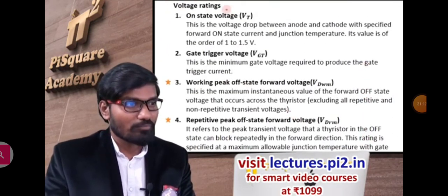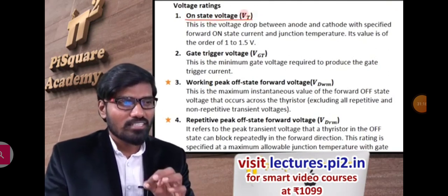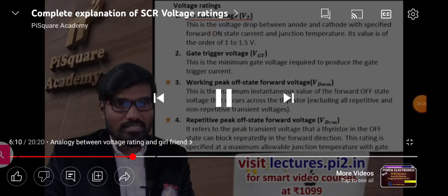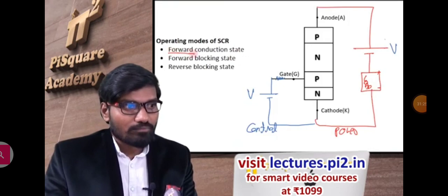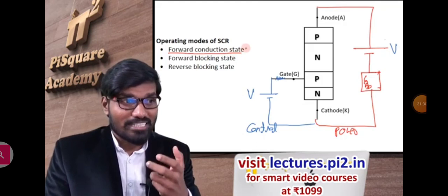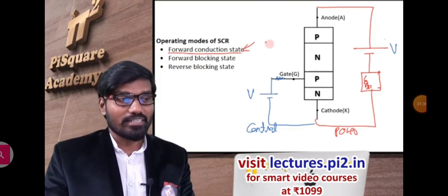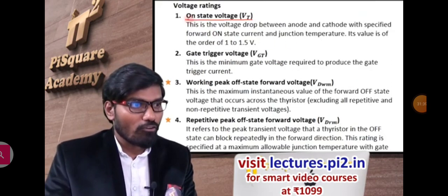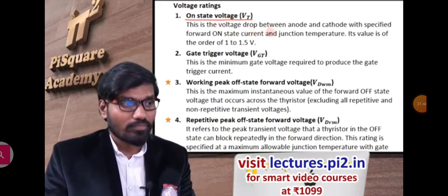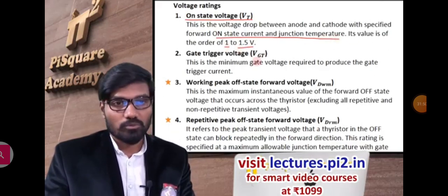Yes, these are the voltage ratings. On-state voltage, simply VT, means when the device is conducting, the forward conduction state. For every state, you specify what the rating is during that state. On-state voltage is the voltage drop across the junction when it is conducting. Normally the value is 1 volt to 1.5 volt.